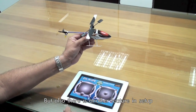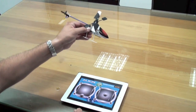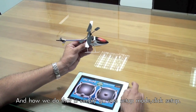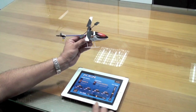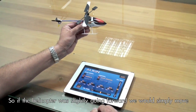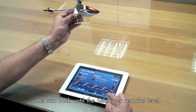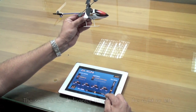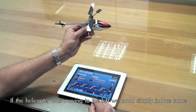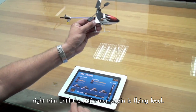But also, there's another feature in setup which enables us to basically trim out the helicopter, whether it be flying forward or backwards, going to right or left. And how we do that is simply go into setup mode, click setup, and you'll notice that there's elevator trim and aileron trim. So if the helicopter was kind of slightly going forward, we'd simply move the trim back until the helicopter remains level. And the same for if it was going to the right or left. In this case, let's use left. If the helicopter was moving to the left, we could simply induce some right trim until the helicopter, again, is flying level.